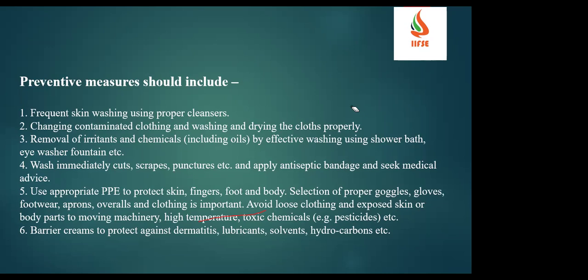So if there are any cuts or damage, we have to wash them out immediately. Then use appropriate PPE to protect the skin, fingers, feet and body. Select appropriate goggles, gloves, footwear, apron and overalls, and clothing is also important. Avoid loose clothing and avoid exposing the skin or any body part to moving machinery.